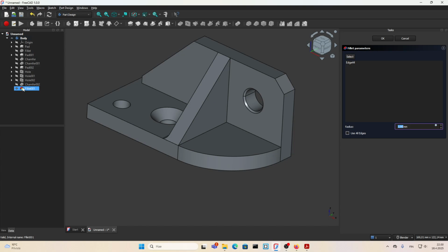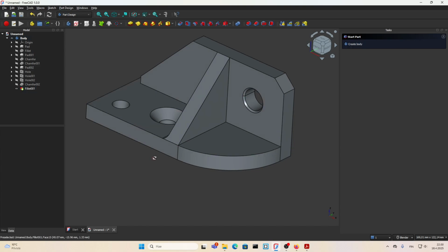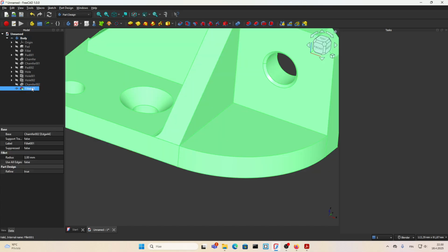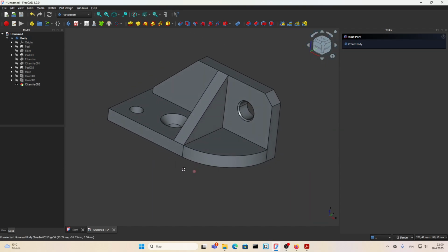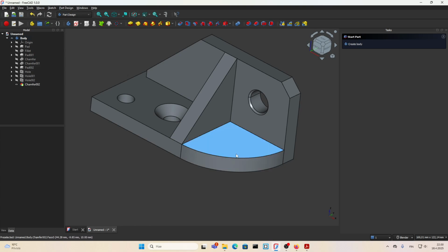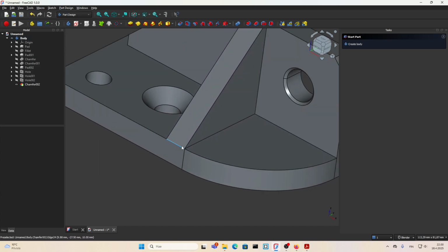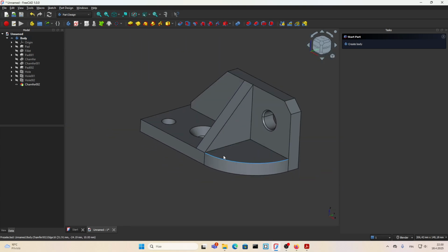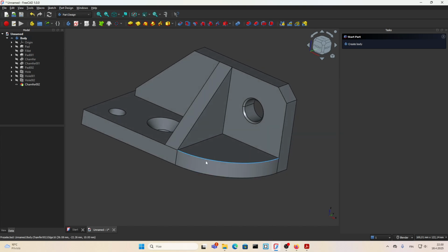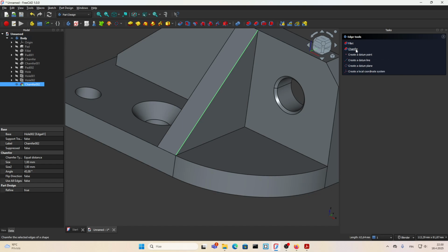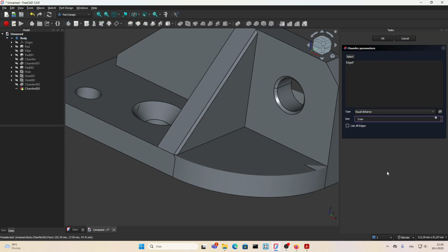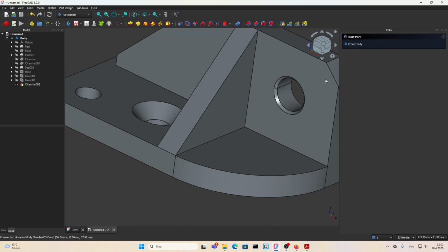That's okay. Let's go back. And now we're in here. I will delete this fillet. I just deleted it. Now I want to keep this 45, just like this. What should I do? The solution that I have found is first you need to delete this fillet, because the first thing that we need to do is chamfer it. But if I chamfer it right now, see what happens? The model gets destroyed.